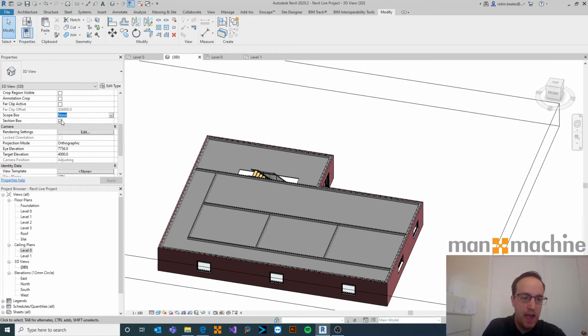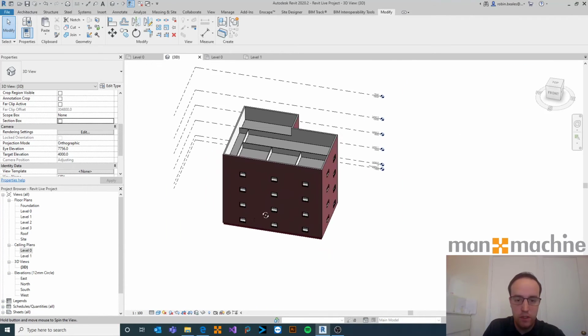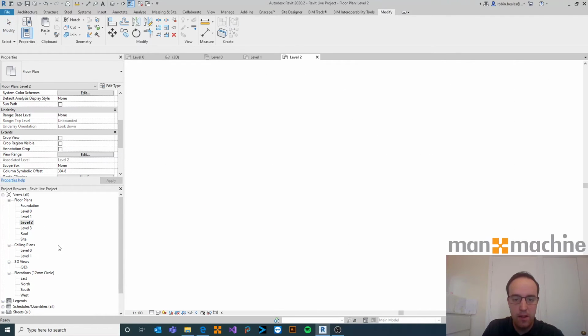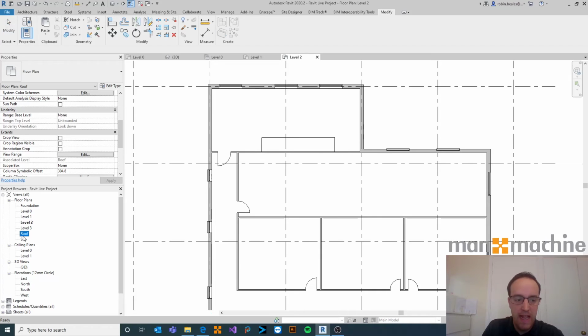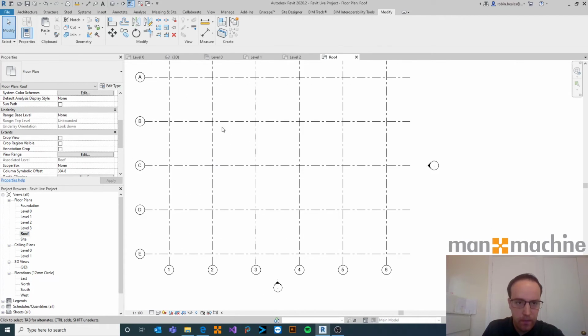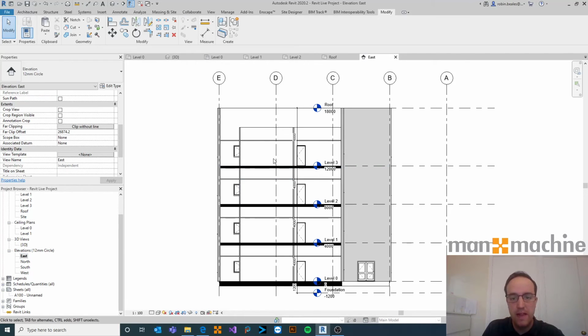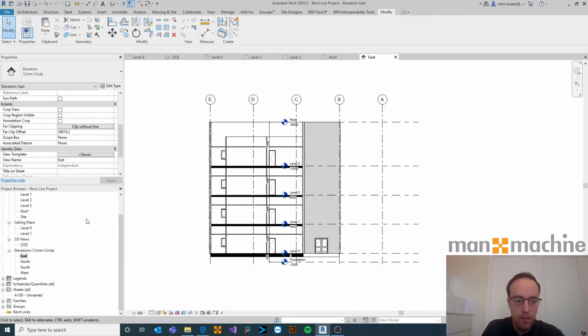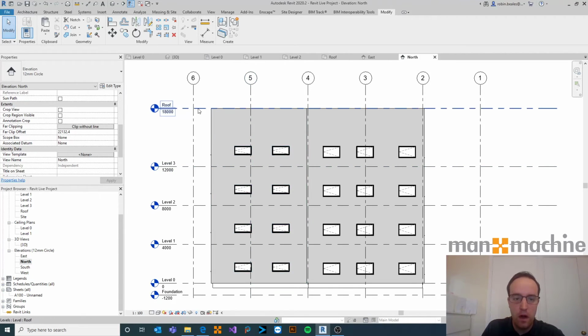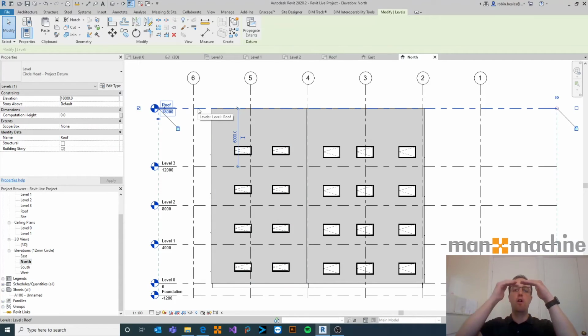Once we've done that, we should have this building spanning multiple stories with all the components in each level, both in 3D and on the floor plan. Finally, head up to our roof level, and we want to add on our roof. So the roof currently doesn't see anything. So if you just have a look at your elevations, just to explain this before we finish off, on our elevations, let's use the north one that we used earlier, our wall stops at our roof level and our roof view doesn't go below that.